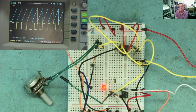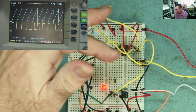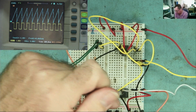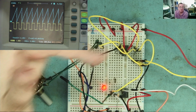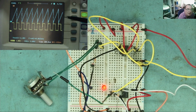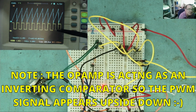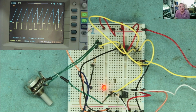Okay guys, and I've built that circuit, we can see it here on breadboard. So this is the 555 timer chip. This one is an LM393 dual comparator, but I'm only using one comparator. And on the oscilloscope, we can see 2 traces. So the cyan one, this is the output from the 555, the sawtooth wave, and the yellow one, this is the output from the comparator LM393.